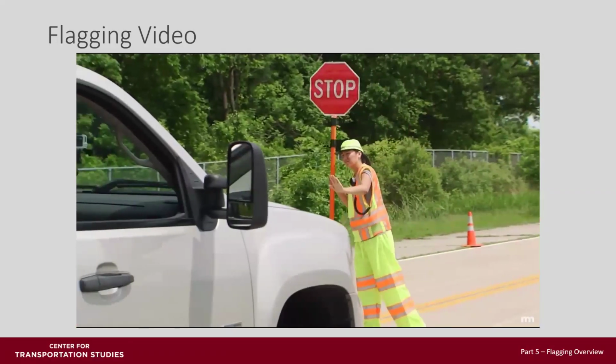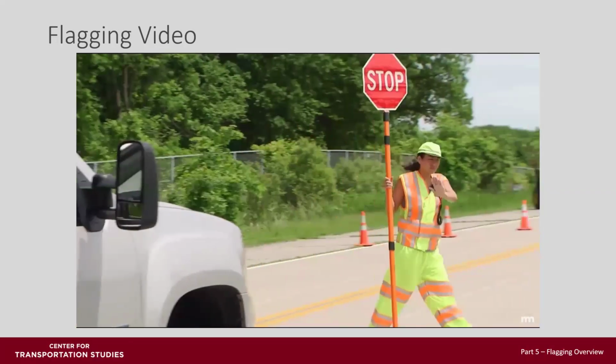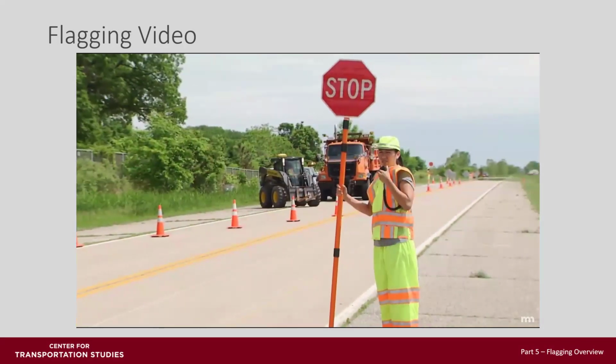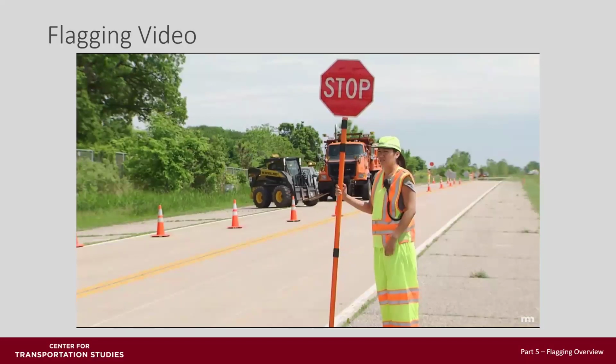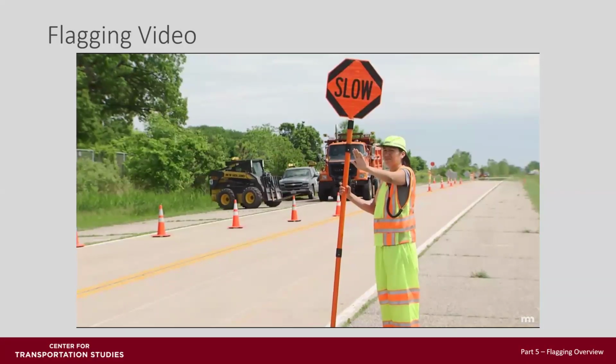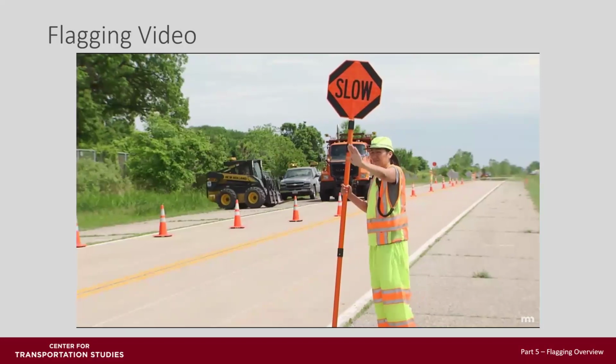When you are satisfied that the drivers of all approaching vehicles are aware of your presence, you should move back to your normal flagging location on the shoulder. Keep your paddle on stop until you are safely on the shoulder of the road. Only then may you release traffic.